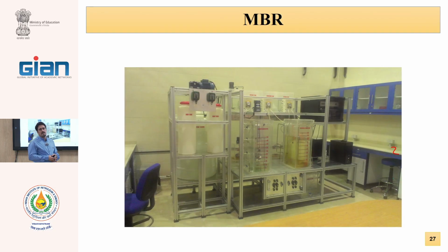In the MBR, we have an activated sludge tank that has microorganisms there, and we give oxygen, aeration, for biological degradation of the organic pollutants, and give some food, some vitamins, some ingredients such as zinc, magnesium for growing of the microorganism, because microorganism is alive and needs food. Without carbon, it needs the minerals also.